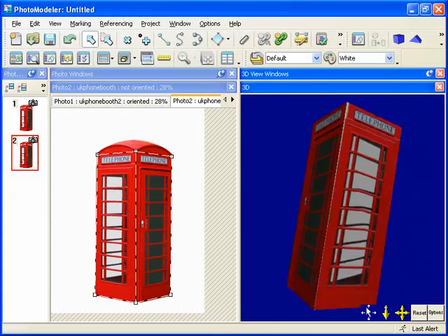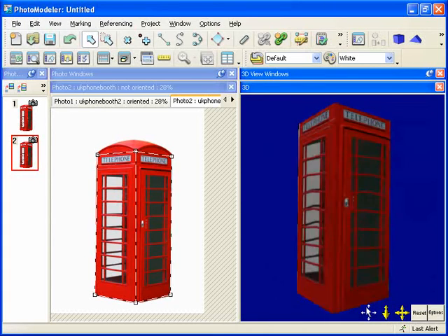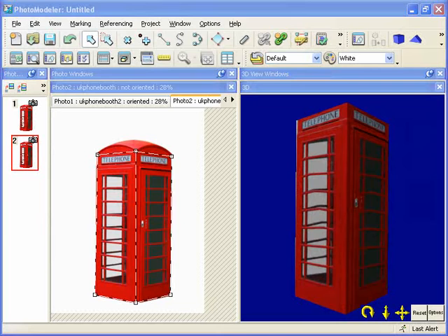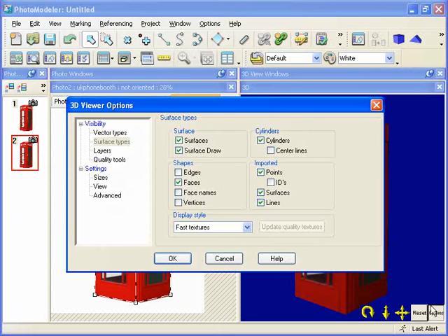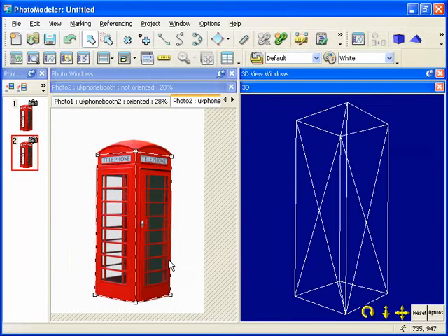And we have rough textures on all sides. We'd like to complete this top part, but we need to use a curved surface. What method can we use to get the surface? The method we will use starts with surface draw and then attach the surfaces to those curves. The surface draw can be started on any surface, in this case, shape face.